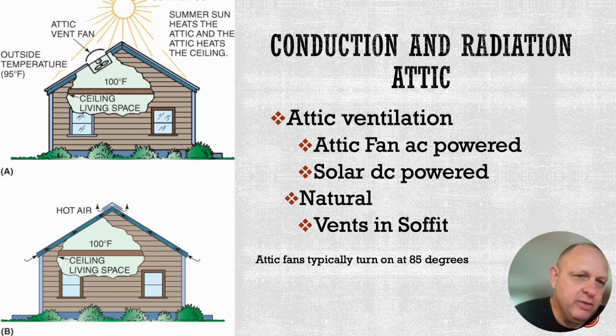I would rather see the attic fan being put in, and then our actual down in the corners, our soffits. If we had a nice little overhang over here, and we had our soffits sitting there, that air would be pulled up our soffits into the attic fan, and that would be a better condition for us to remove the heat in that structure. Not saying that you can't install an attic fan with a ridge vent. It's just that for practical reasons, when we're dealing with a path of least resistance of airflow, it tends that the attic fan will suck through that ridge vent.